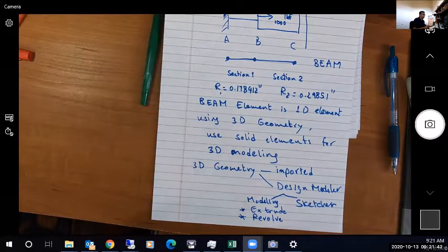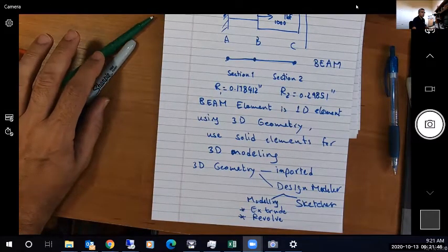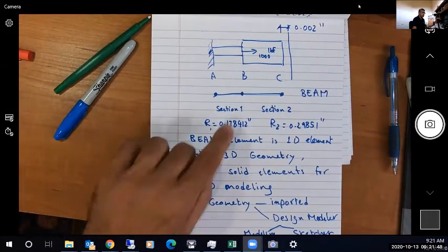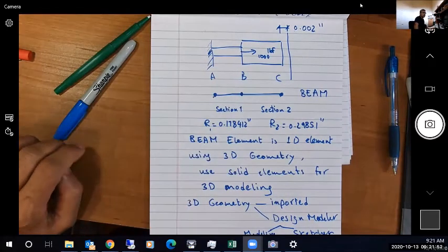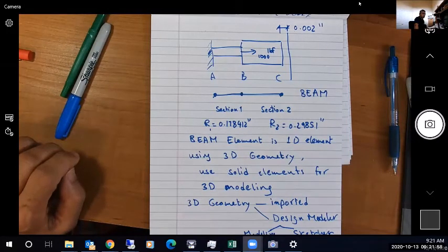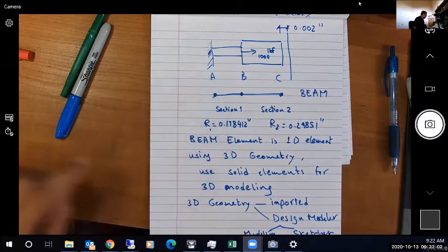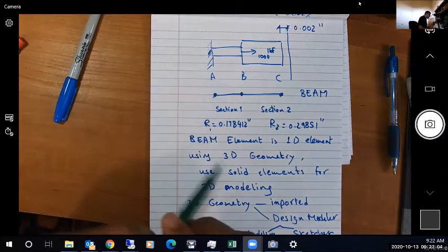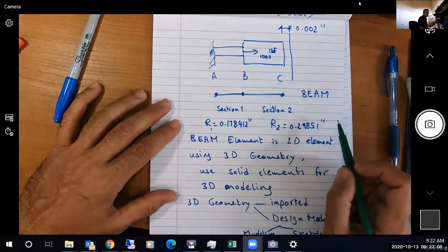These are the two functions that we're going to be using to create geometry in this class. All right. With that being said, I would like to go create this geometry in Design Modeler as a 3D model. So if you look at this, I can look at either revolving or extruding.